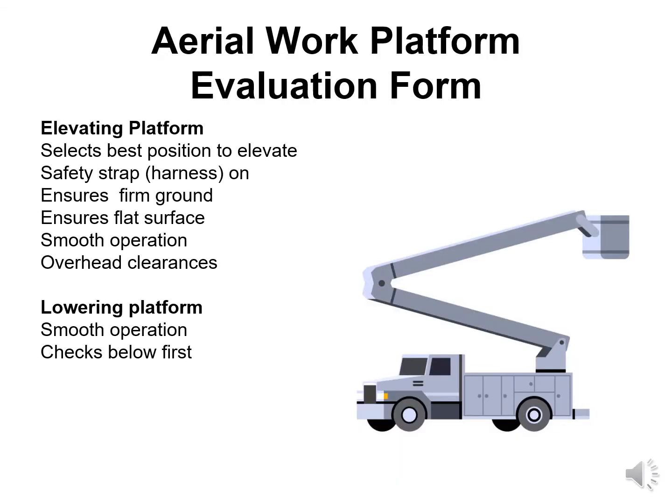Aerial work platform evaluation form continued. Evaluating platform, select the best position to elevate. Safety strap harness on, ensure firm ground, ensure flat surface, smooth operation, overhead clearances. And then lowering platform, smooth operation, we want to check below first.